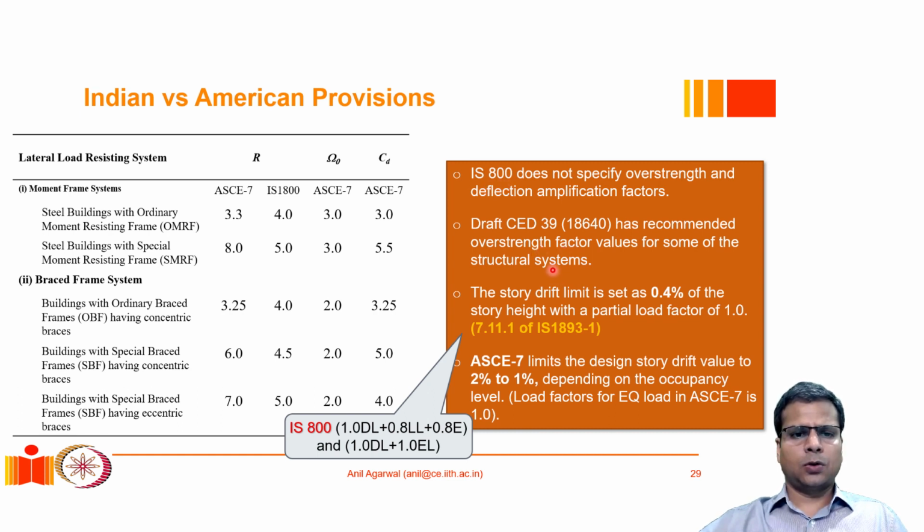Okay. So, IS 800 does not mention the overstrength factor, but as we have seen before, it uses some load combinations for the design of capacity-protected type of components, and those amplification factors, the load factors, are nothing but the overstrength factors. For the limit state of serviceability,